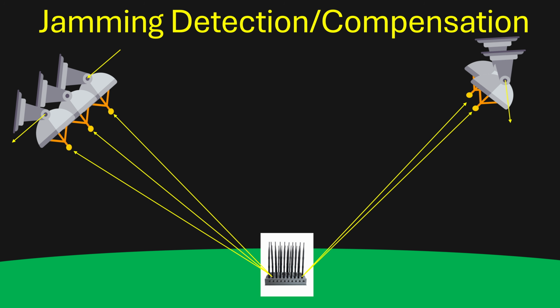The only problem with jamming is that you are broadcasting a signal from your position. These satellites are incredibly sensitive, so all they have to do is turn off their transmitters and switch to a signals intelligence mode, and they could probably geolocate the signal very quickly. A single along-track interferometry satellite could probably geolocate almost any jamming. And then if they have knowledge-aided distributed space-time adaptive processing, they could probably detect and then cancel out jamming in